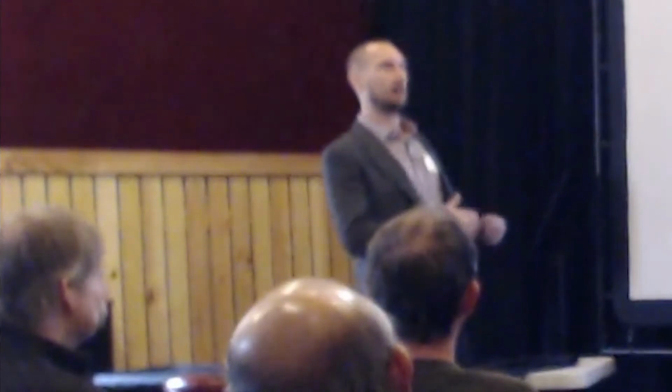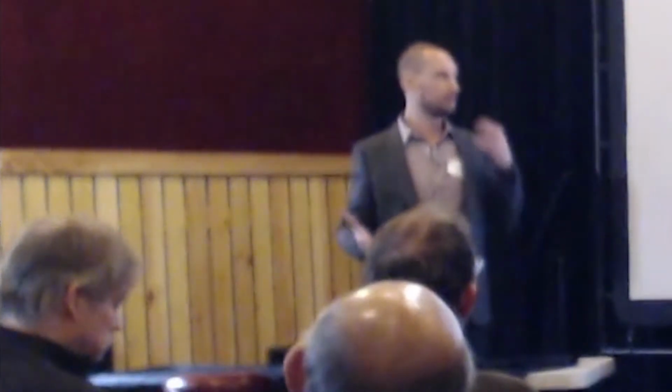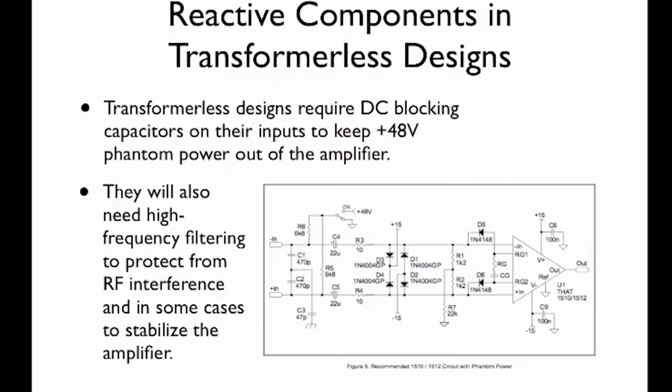When we're talking about creating a 6 dB per octave filter to avoid getting any annoying interference in, we need to begin rolling off low enough that we can avoid getting a significant amount of that radio frequency into our circuit, while also making sure that we keep at least 20 kilohertz bandwidth. Okay, next one.